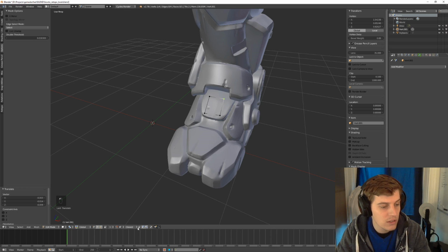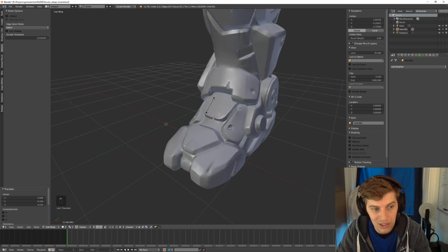And then this one, I guess I can't really illustrate because I need a mesh that allows me to snap onto itself. And at the moment, this is just a polygon. So I'll just turn all of these on. Then the merge automatically, which is this button. This is off. This is on. If I drag two verts close to each other, you'll see they'll snap to each other and basically merge.